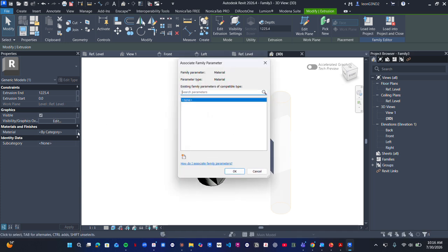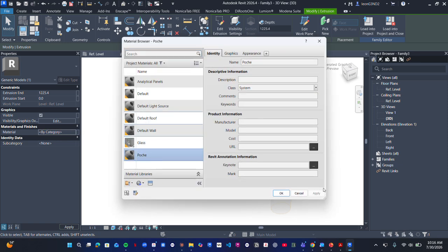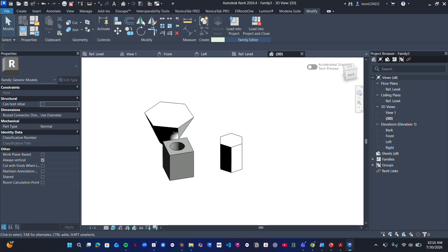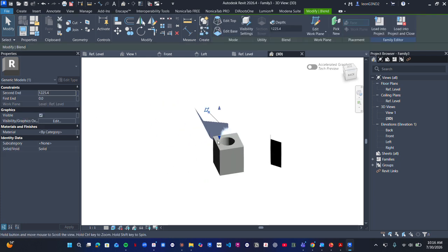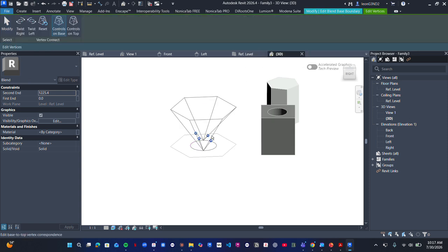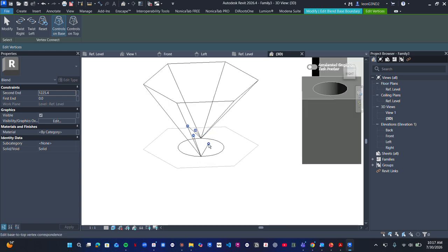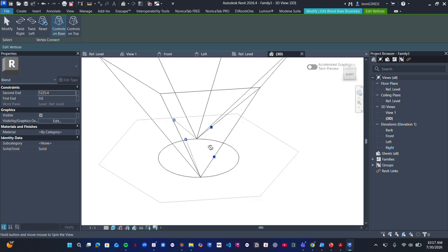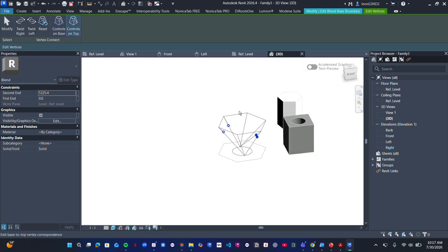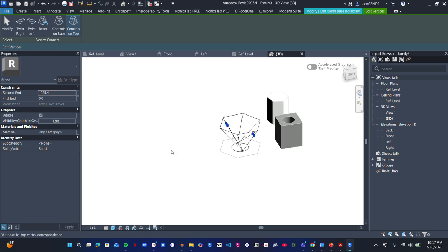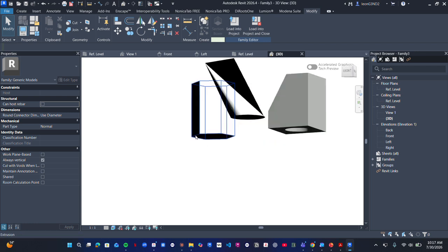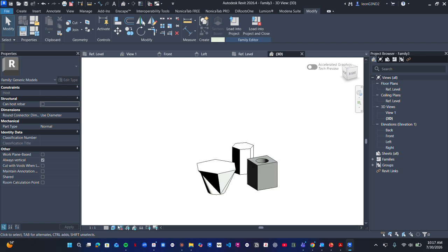You can actually set this. So you can also just create a parameter to it, or just select an actual category. These are just some things to keep in mind as well. So, the various tool types that you can create, and then also, like I said, you can edit vertices. So if I am editing this, when I am changing this, I can just say edit vertices. I can actually just change where these land. So you can say twist right, twist left, controls top. Just elements that you can manipulate, and say okay. So you can see here it starts to create this interesting shape.